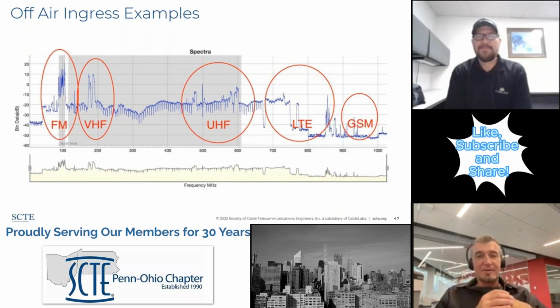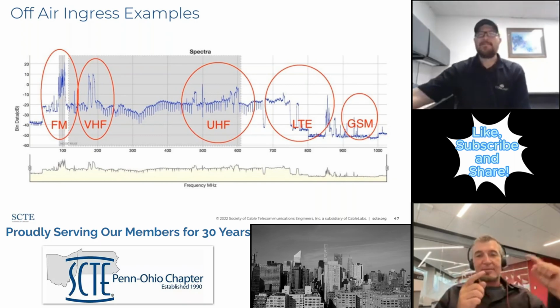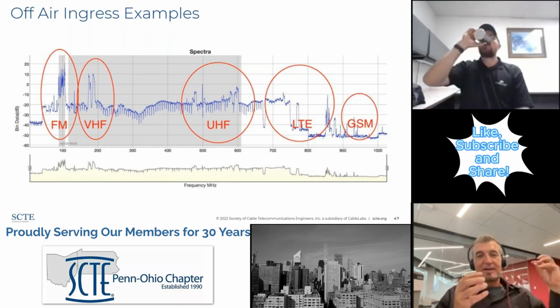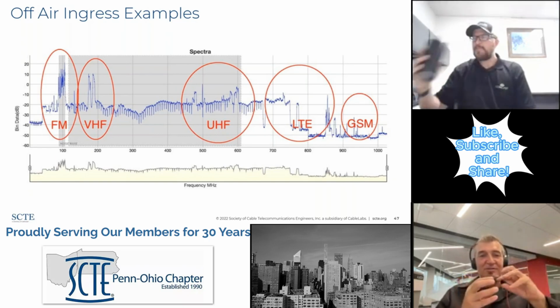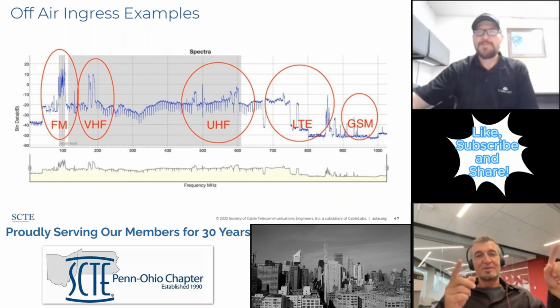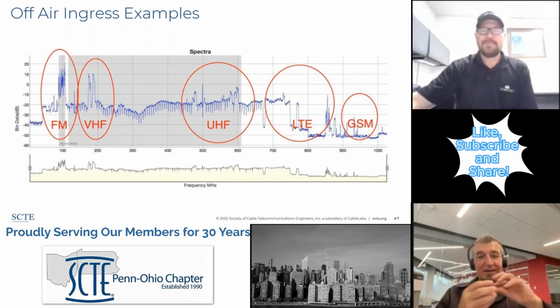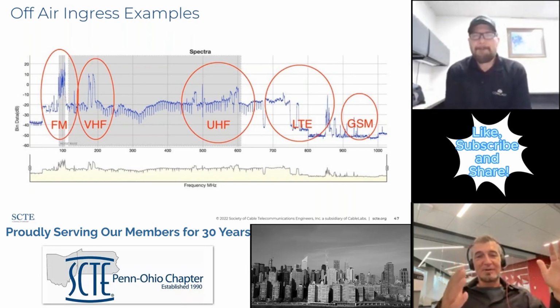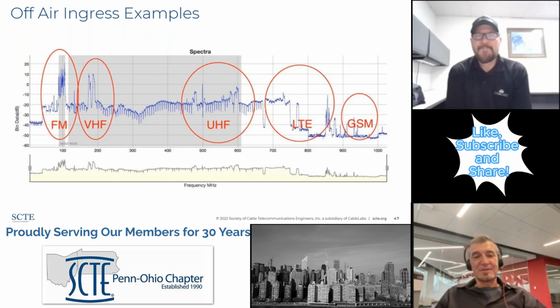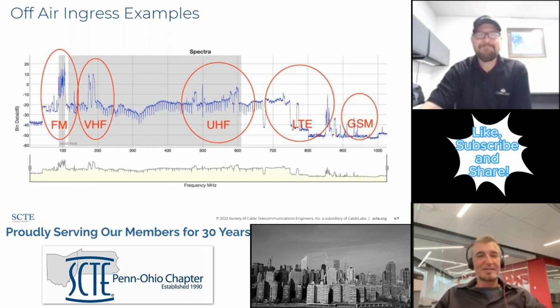There's a recent example of a cable coming out of the side of a house, and the dog had chewed and stripped all of the shielding off, and there's about a 6-inch center conductor with no shielding whatsoever. This is exactly what that frequency spectrum would look like in that case. Unfortunately, more common than you would hope or expect to see. But it's out there.